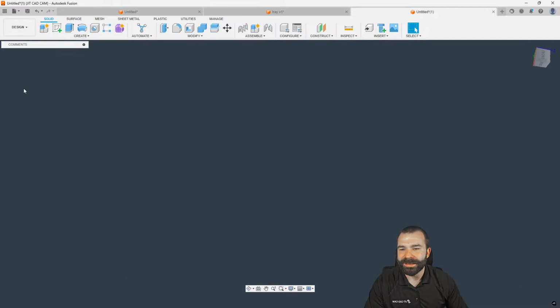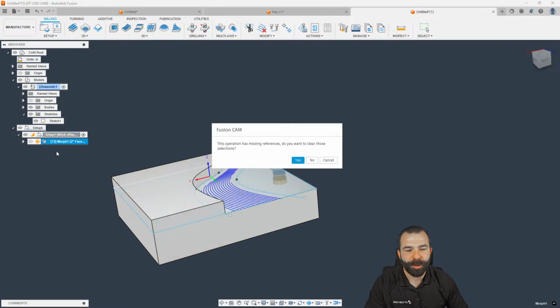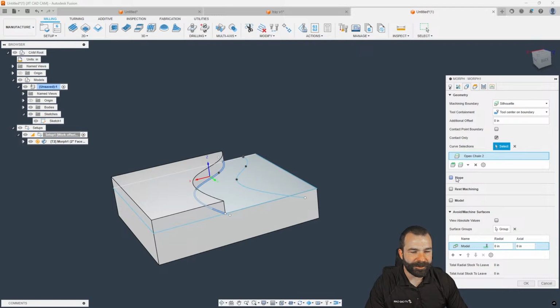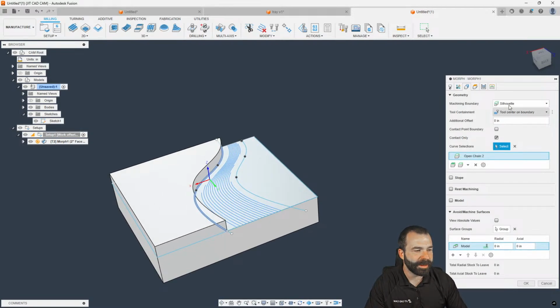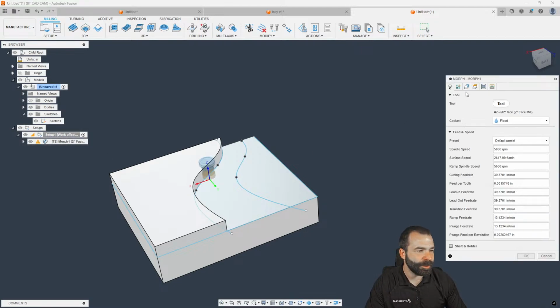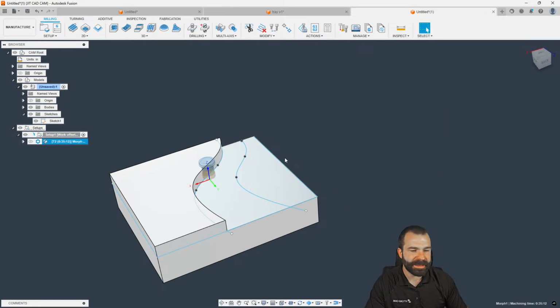Let's go ahead and remove this side here. We open back up. We now have a three-sided open kind of profile. We no longer are actually going to use that first guide curve. So you see me removing that. And what we're getting is an error: no path to link, empty toolpath. And that could be because it needs two guide curves. So let's go ahead and give this another guide curve and see what we get.